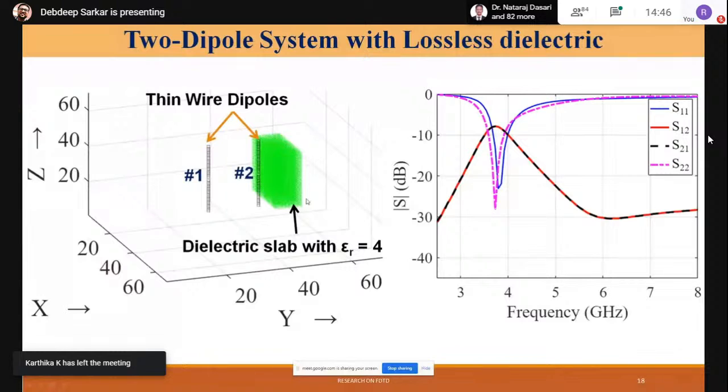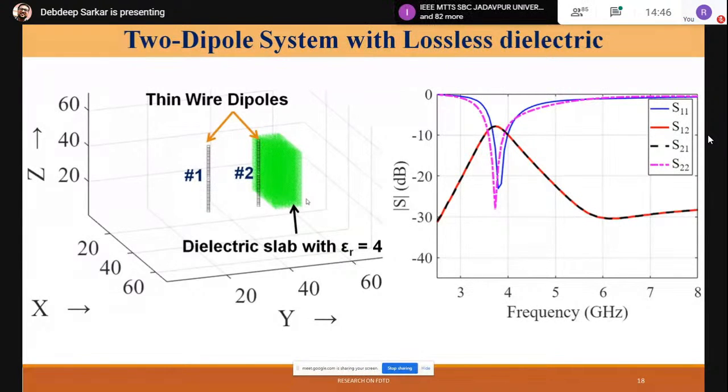So you can use this kind of a framework. Of course, there are several solvers available, but the beauty of this is just a few lines of code for a 3D-FDTD routine. The principle is exactly the same that I followed yesterday, the 1D FDTD, only extended to more memory. Instead of 1D matrices, I now need to store 3D matrices. And of course, the PMLs and all have to be implemented. But you can simply write it, and you can see that your results can be validated by existing commercial solvers.